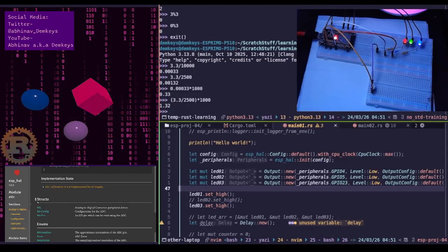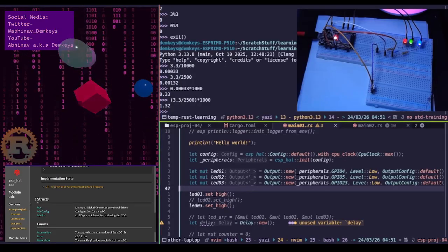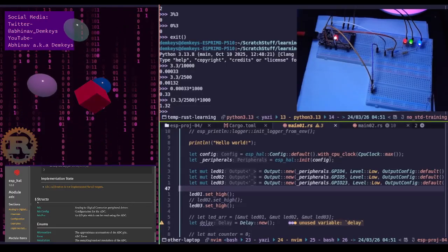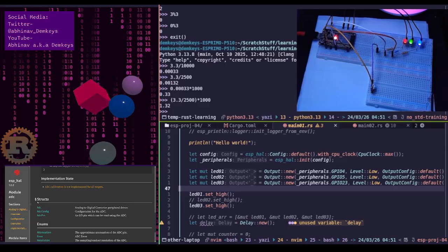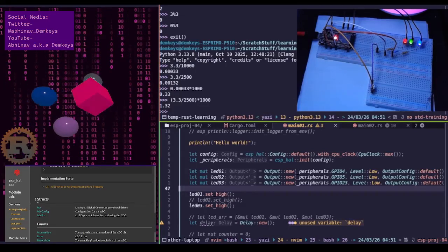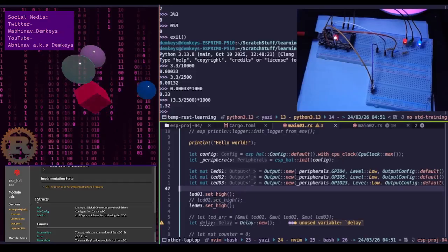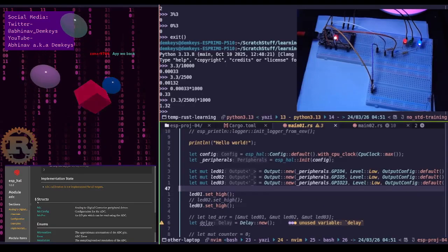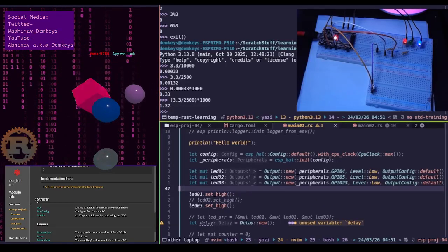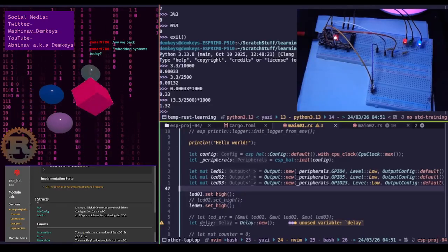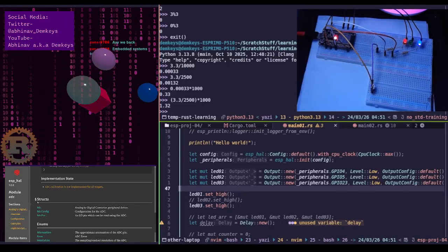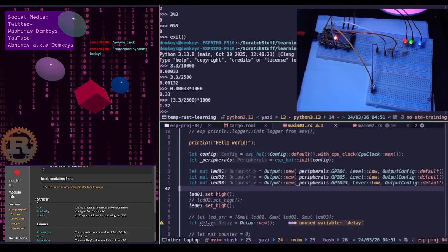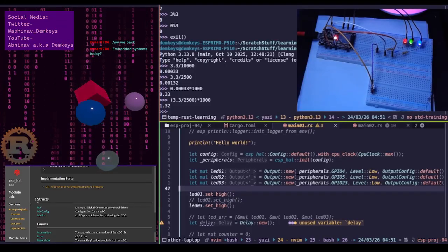However, your potentiometer has a fixed resistance, usually 10K, between the 3.3 volts and ground pins, between VCC and ground. I equals so-and-so. Right, so this comes back to our 0.33 milliamps current. That is a tiny amount of current. It's like a slightly leaky faucet rather than a fire hose. The resistive material in the pot is, quote unquote, consuming that energy and dissipating it as a microscopic, unnoticeable amount of heat.